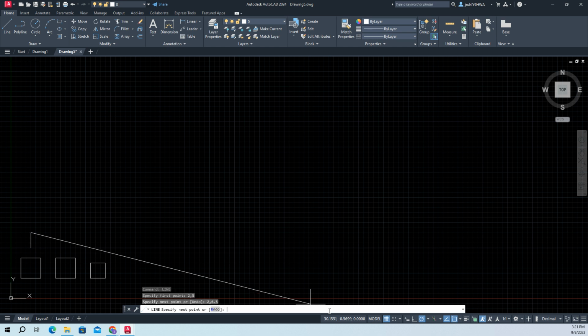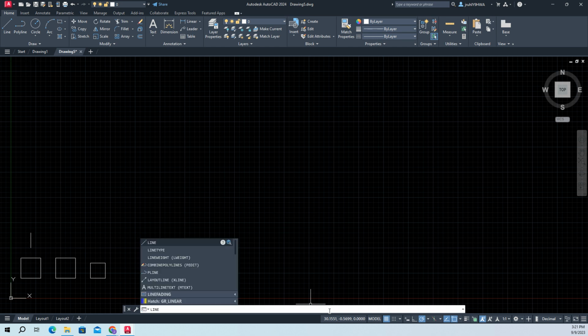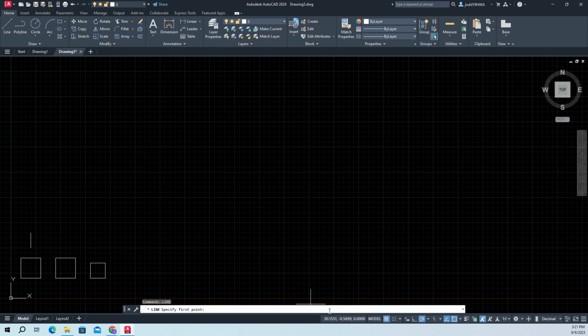So draw a line from 2 to 2 points. Okay, good. And then they want me to draw another line, so I entered out of it. Now I got to hit line again, select it, line 1 comma 6, enter, 3 comma 6, enter. Now I have my 2 perpendiculars.